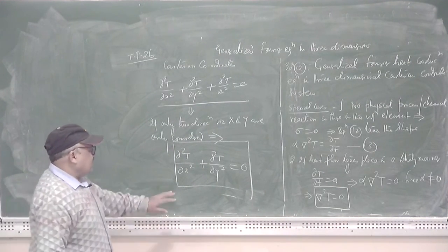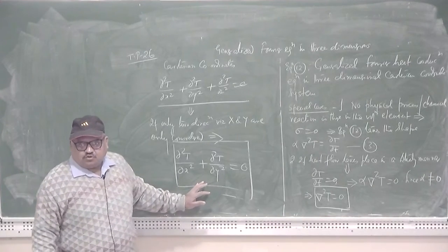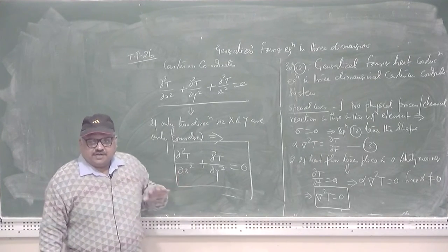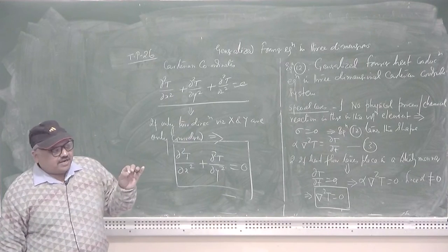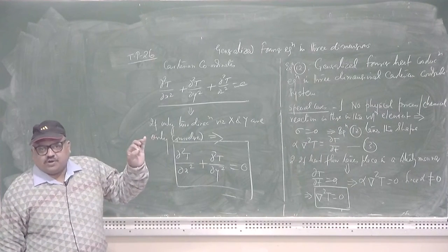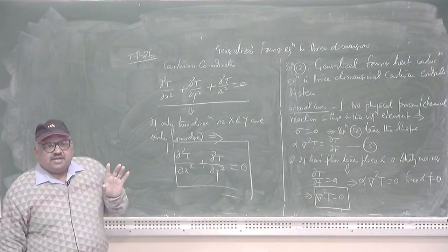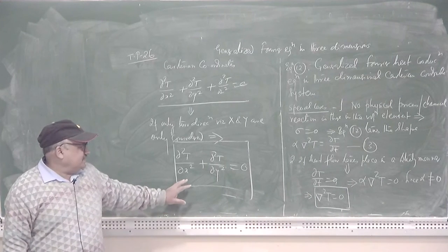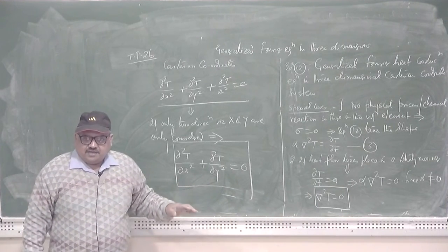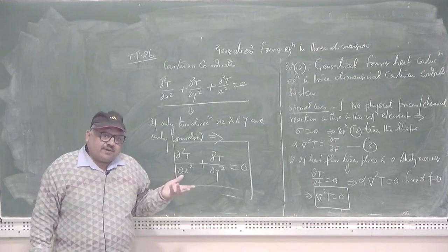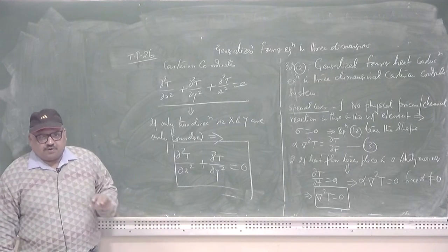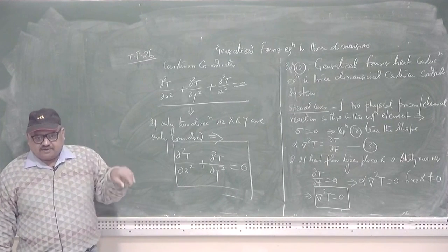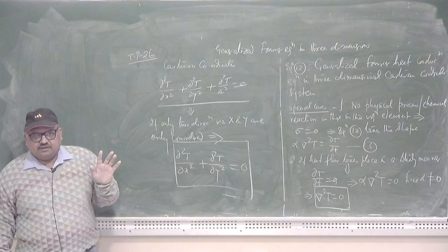This equation is of immense importance so far as the numerical evaluation of the temperature at a particular coordinate in a 2-dimensional plate is concerned. This equation is utilized along with the finite difference techniques to develop the nodal equation for each and every node available in that particular 2-dimensional body.